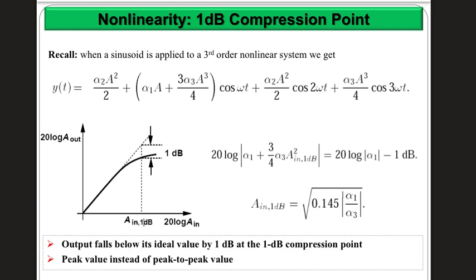Okay, so your amplifier, for example, comes with some specs. Typically, in your power amplifier or even low noise amplifier, you have specs that talk about the gain or the amplitude of the harmonics. So this is the amplitude of the second harmonic, third harmonic. And they also give you something called the 1 dB compression point.